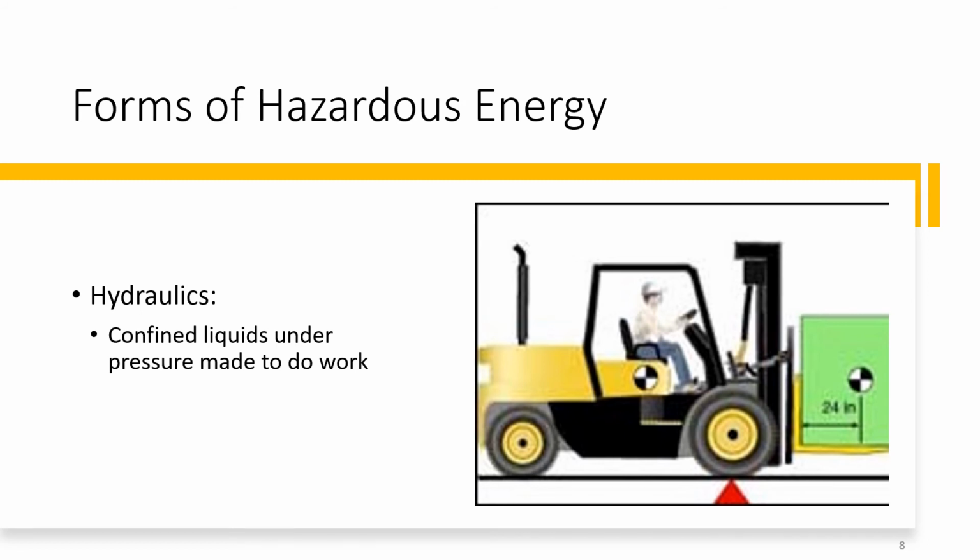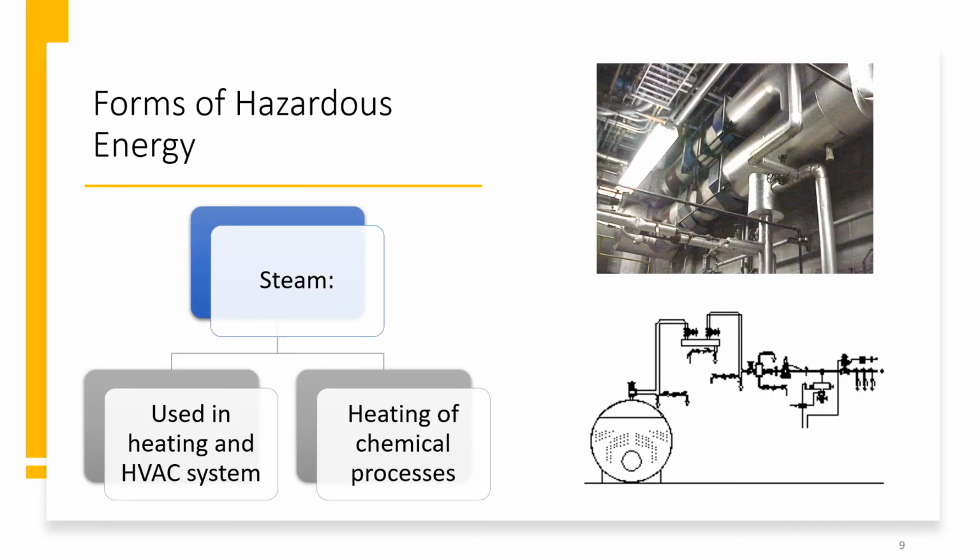If you have to go back and do maintenance on the forklift, you may have to look at how do I make sure that, if I have to, or if it even happens by accident, the hydraulics are going to stay in place. And that's why typically a load is always dropped. You're going to put some kind of bracing under it, because if the hydraulics are let go, not only do you have all that pressure involved too, but whatever was elevated will now be coming down as quick as possible to the earth. And that's hydraulics. We'll go on to the next one here.